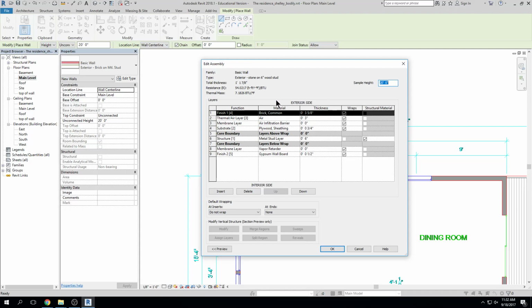We notice that we have the exterior side here, we have the interior side here. If I hover over the number, click, I get a little black arrow, and if I click, I select those items. If I come over here, you see my regular cursor pops back up, and I can click on a function and use the drop down and find the function I want, okay?